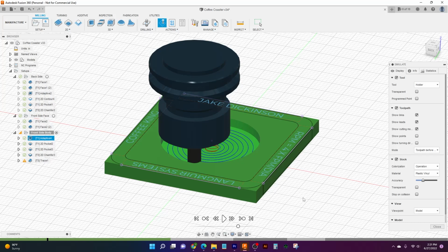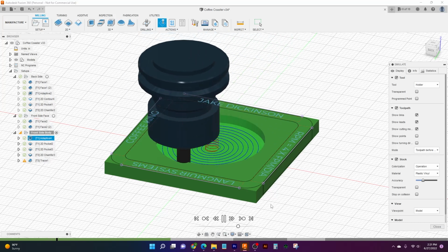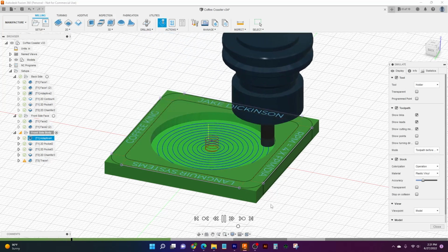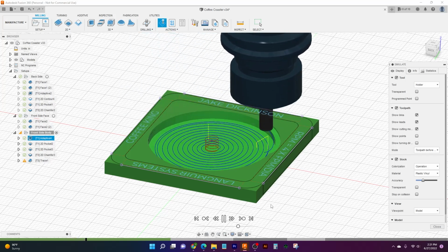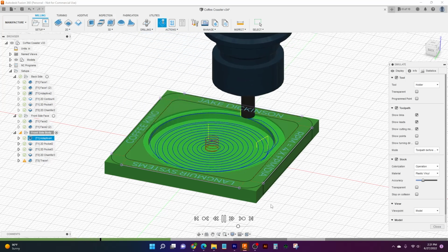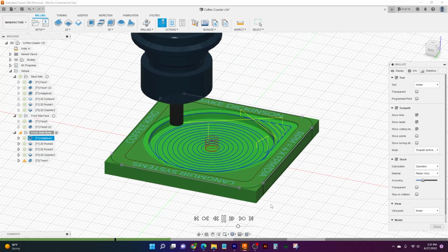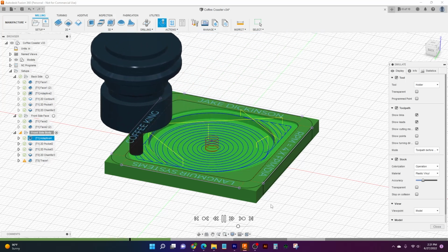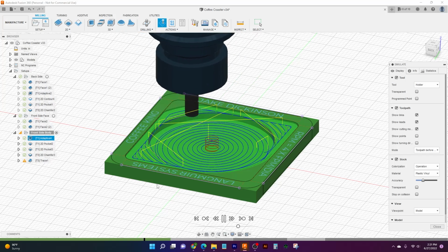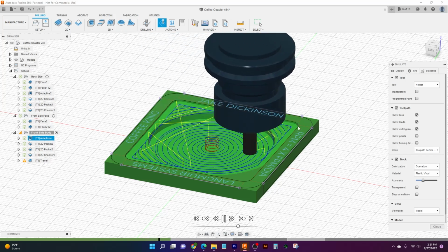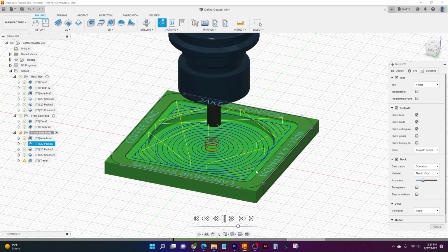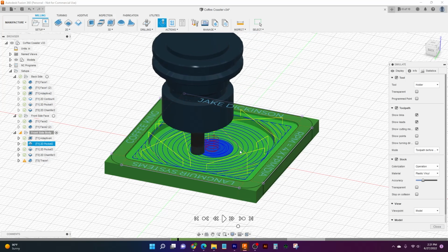And like machining, there's always a million different ways to achieve the same results. And everyone will come up with something that they can do their own way. And so let's keep going here. It's going to chunk out all that bottom, and then when it gets to the outside, it's going to come up and it's going to do the top. And it'll jump from one corner to the next, cleaning up those outsides, but leaving our 5 thou on the walls and our 5 thou on the floors. And then we're going to come into our finish.